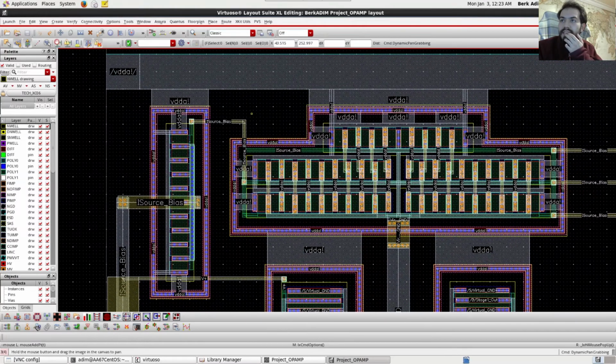As you can see, their source resistances are scaled down with the width. So when we scale transistors up in width or in gate values, we must scale their source resistance down if you want to have the same source voltages.